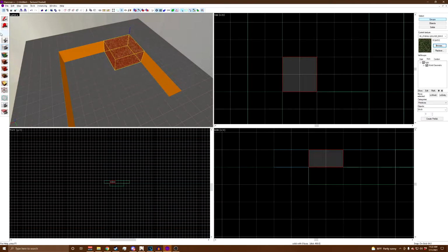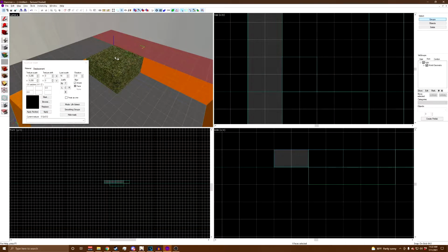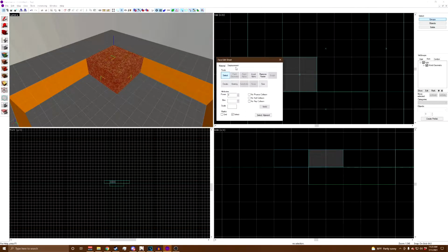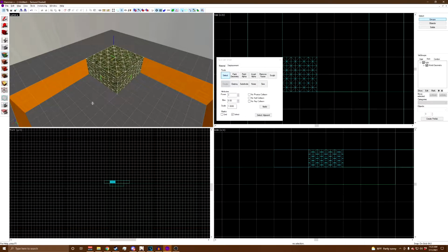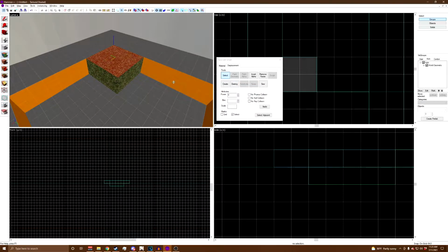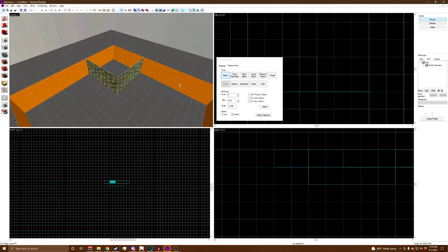You can turn any brush that you've created into a displacement. Simply select it, go to the Texture Application tool, go to Displacements, and hit Create. This will turn all selected faces into displacements. And this brings up the first rule about displacements, which is to only select the faces that you wish to turn into displacements. Once you hit Create, all non-selected faces will no longer exist. And this is what you want when displacement mapping.